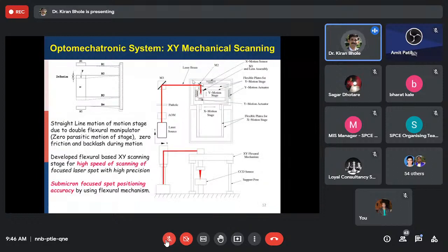Now, how to develop this on-axis scanning scheme? The concept is very important, which we have discussed, but how do we develop this scanning scheme? It consists of four linkages. I told you initially that in the conventional straight line mechanism, we have two rigid bodies connected with a pin joint. A pin joint has clearance of itself, in microns, and that's why it cannot be used.